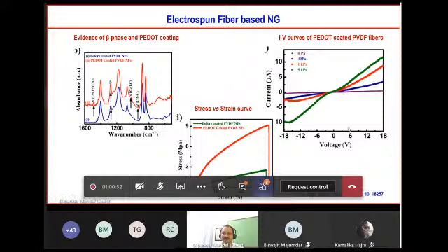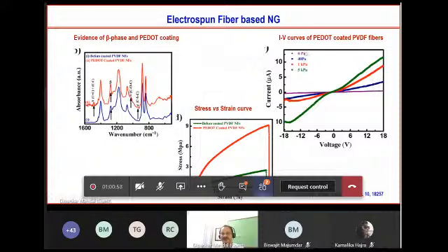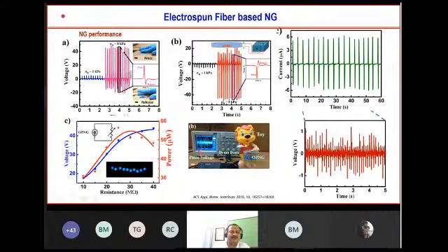And we are also very familiar with the IV characteristics in physics. If we apply different stress and different pressure, you can see we can improve the current, right? So end of the day, we have a device like this. You see the top and bottom electrode, and this is our hand. If we impart by hand different force or pressure amplitudes, you can see 1 kilopascal here and 8 kilopascals, then we can produce around 40 volts of voltage, and the current is around the 6 microamps order.